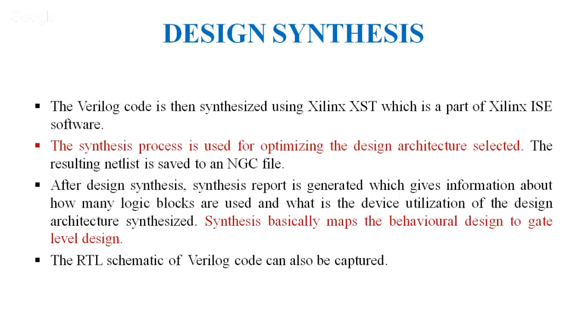The third step is design synthesis. Design synthesis is basically used when we do implementation of our code. The synthesis process is used for optimizing the selected design architecture. The netlist is saved in the NGC file format. After that, a synthesis report is generated, which gives information about how many logic blocks are being used.